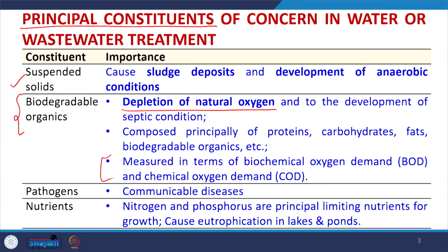Now, all these biodegradable organics are measured in terms of biochemical oxygen demand and chemical oxygen demand. For biological wastewater treatment, this is one of the most important criteria. So, we will be learning this BOD and COD in detail in today's lecture or later on.